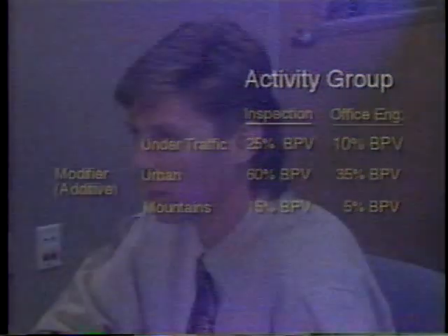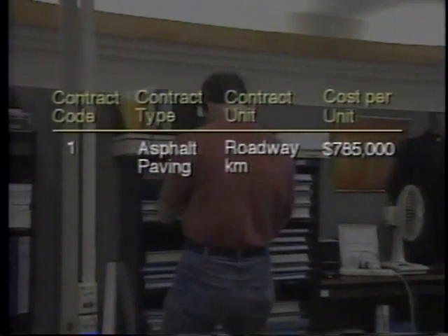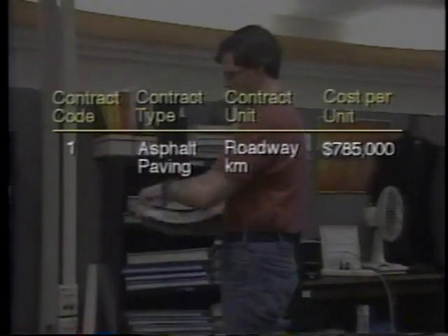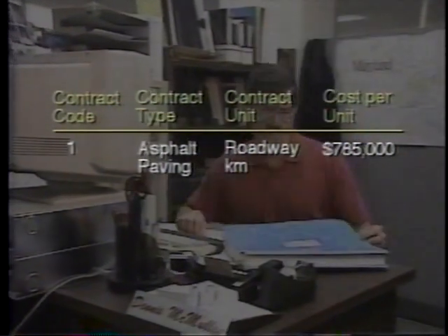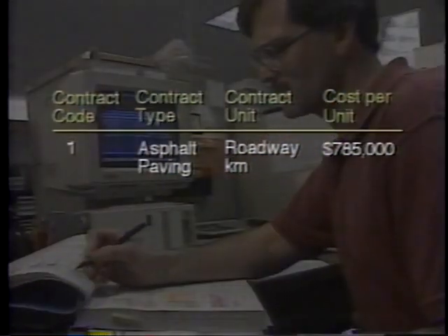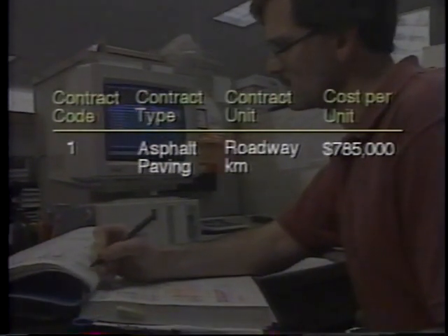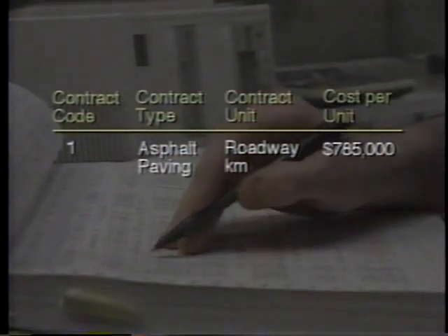For some construction programs, neither detailed quantities nor defined project limits have been established, but program budgets are available. Where this is the case, manpower requirements may be estimated by using dollar conversion standards. The cost per planning unit is estimated. The dollars are converted to equivalent planning units, and man-hours are planned using the standards for the planning activity groups.